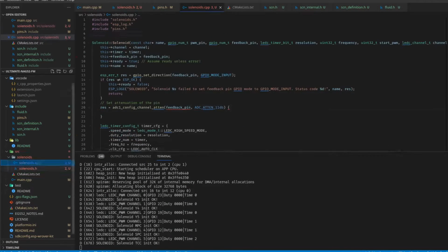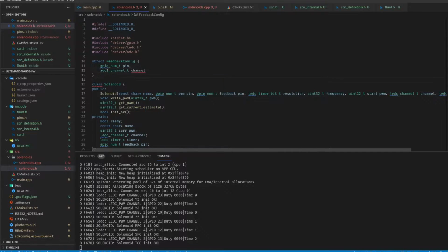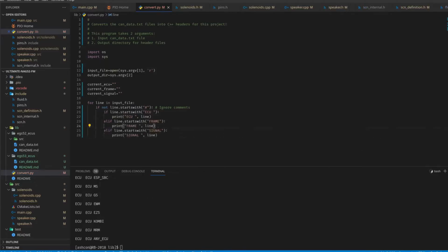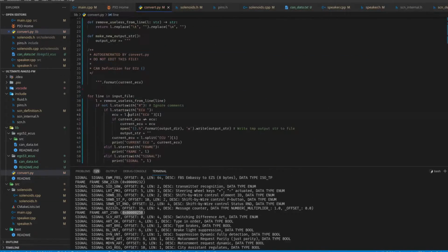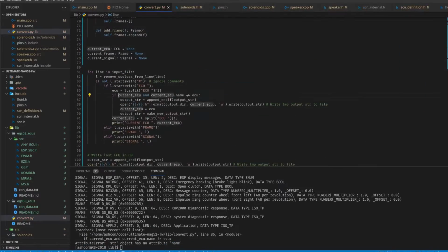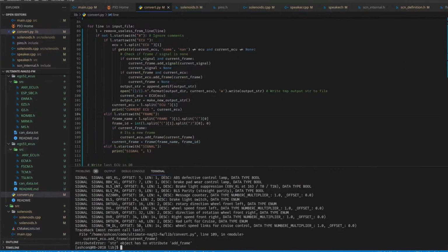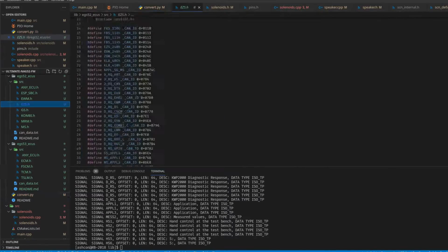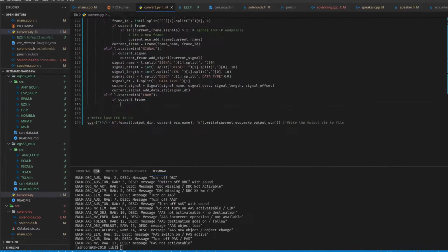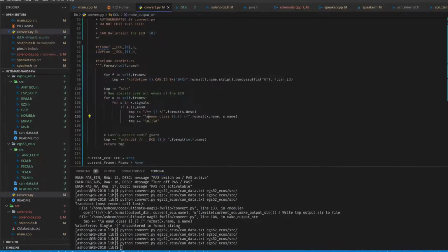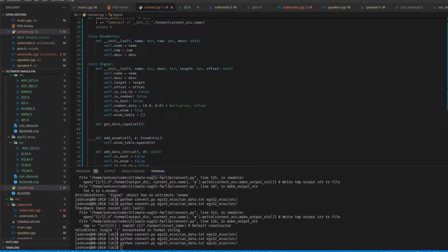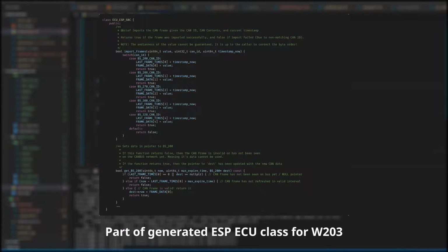Next, I set out to work on adding CAN bus support to my TCM, which is the main goal of this project. To start with, I set about writing a Python interpreter to parse my CAN matrix files from my old head unit project into C++. This parser generates a C++ class for every ECU described in the CAN data files, and structs for every CAN frame as well as correct enum definitions. I then passed both CAN matrix files for the EGS52 CAN networks and EGS53 CAN networks. Here are a couple examples of the script output files.